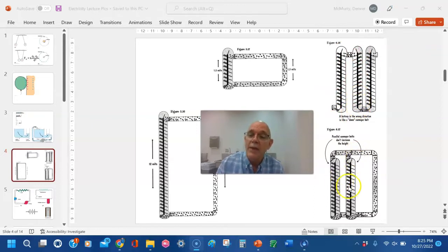You can put them side by side, but notice they still only bring them up a certain amount. So even though you have two batteries, let's say this is 6 volts and this is 6 volts, these electrons only have 6 volts because they're all being lifted to the same height. Since they're sharing the work with these two batteries, they will last longer and bring it up to 6 volts for a longer time. We say that these two batteries are in parallel. They will only get up to 6 volts, but since you've got two of them sharing the work, they will do it for a longer period of time.